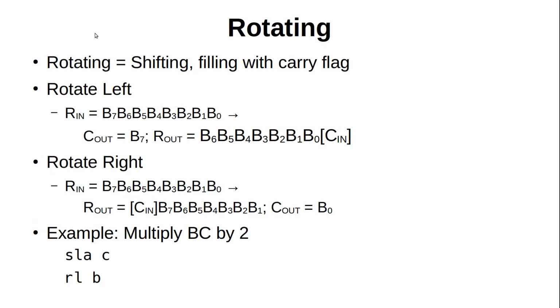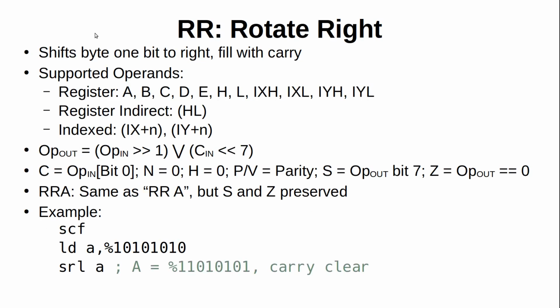The Z80 also has various rotate instructions, which is why all of those shift instructions shifted their leftover bits into the carry bit. The rotate instructions will take this carry bit as an input, as well as the original value, and this lets us string together a shift and some rotates to do a shift across multiple bytes. A rotate will take in the carry bit and shift out a new bit into carry for the next instruction. The rotate right, or RR instruction, will shift the register or memory value to the right, filling in bit 7 with the state of the carry bit, and then setting the carry bit with the value's previous bit 0.